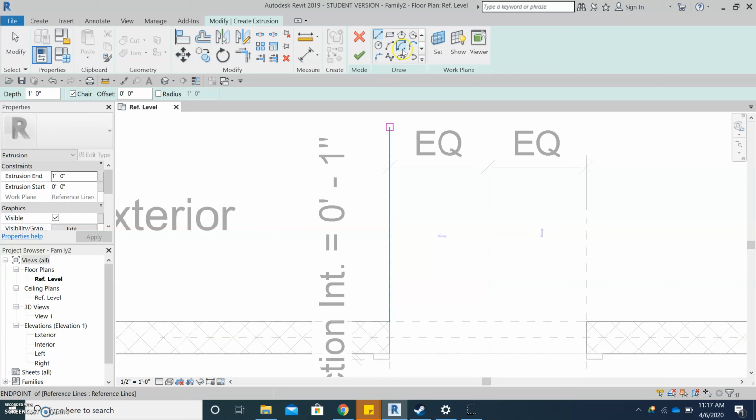So you'll want to do a rectangle, start at the end point of your door panel. It offers us a lot of locking options, but you'll only want to pick locking it to the reference line. That means it can move back and forth still.